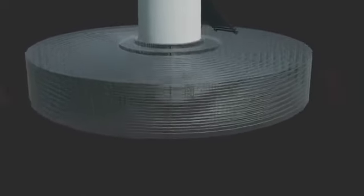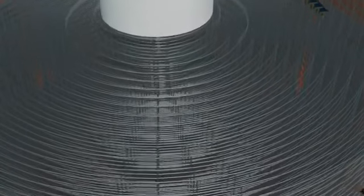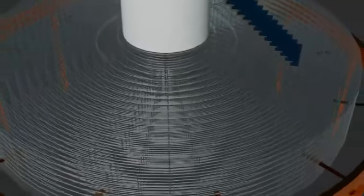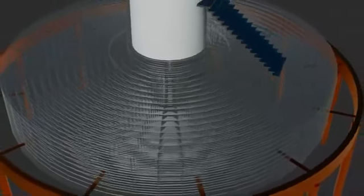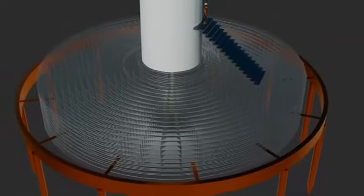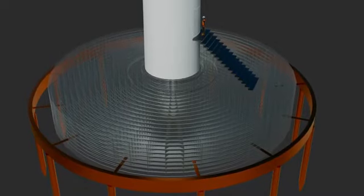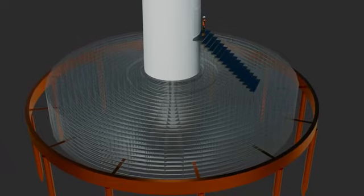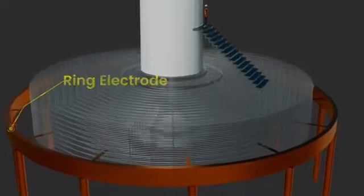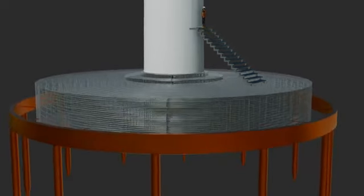The primary grounding electrode is the interconnected network of steel reinforcing bars embedded in the concrete foundation. Using special clamps and welding, this rebar cage becomes one massive, electrically continuous conductor. The large total surface area and intimate contact with concrete and surrounding soil make this an extremely effective electrode for dissipating electrical energy. The steel foundation rebar is connected to a ring electrode, a continuous copper or copper-clad conductor, installed around the foundation perimeter, typically buried 0.5 meter to 1 meter below grade.